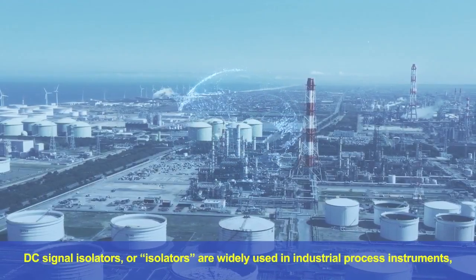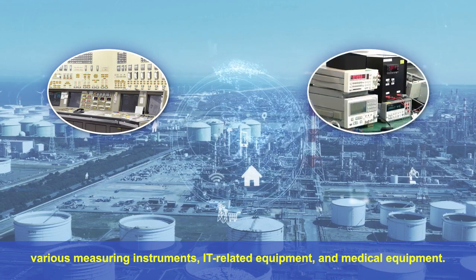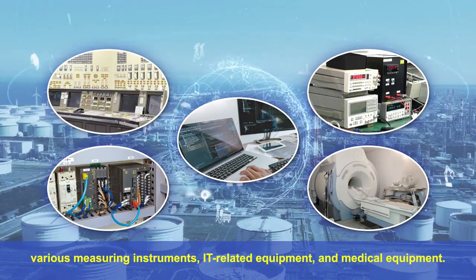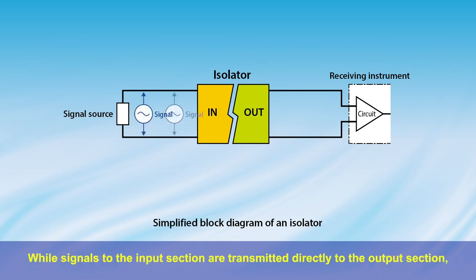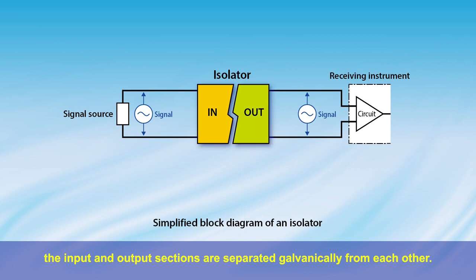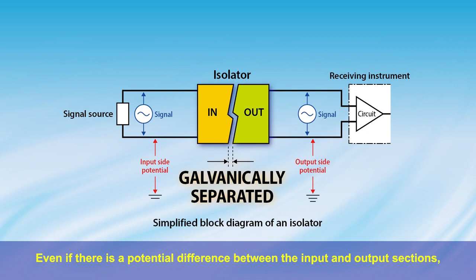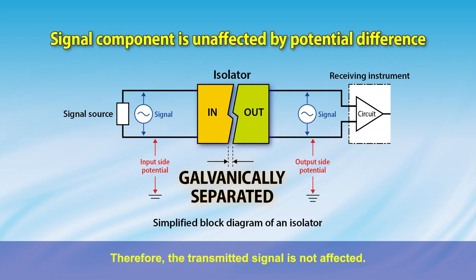DC signal isolators, or isolators, are widely used in industrial process instruments, various measuring instruments, IT-related equipment, and medical equipment. This block diagram shows a simple explanation of how an isolator operates. While signals to the input section are transmitted directly to the output section, the input and output sections are separated galvanically from each other. Even if there is a potential difference between the input and output sections, no current flows between the sections. Therefore, the transmitted signal is not affected.